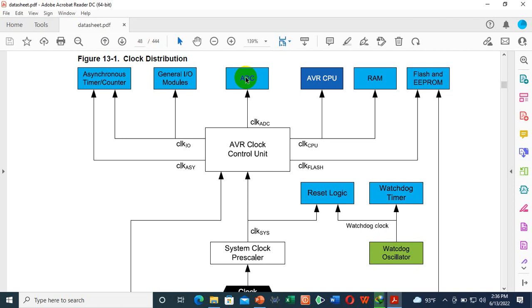So that's the job of the ADC. When you convert, then you can analyze that information. Let's say the maximum intensity of light is 5 volt. If you get a value of 1023, then the microcontroller knows that this is maximum intensity. If it is 50%, 2.5 volt, then you get a value around 511, and you know it is 50% intensity.